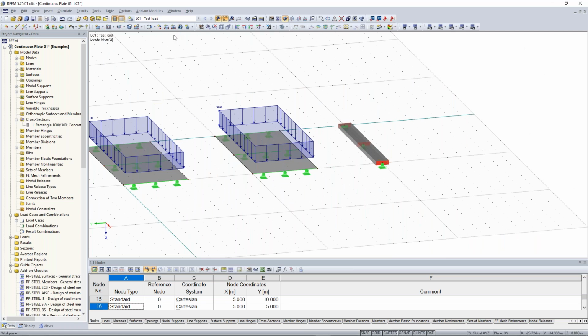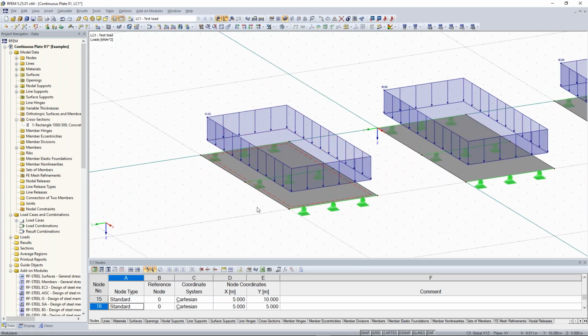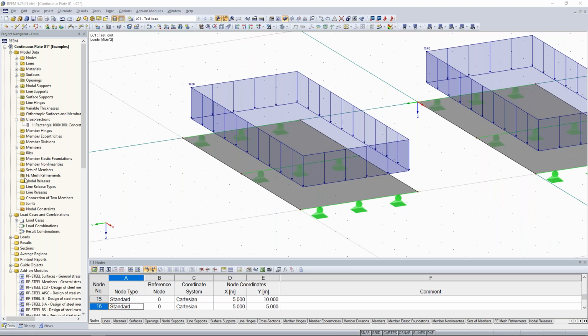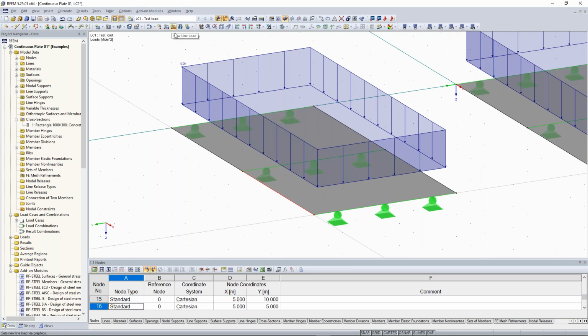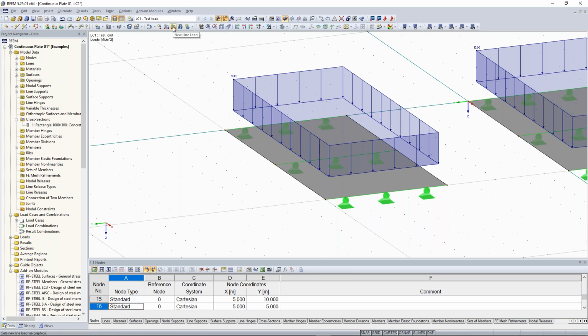One big mistake, especially for RFEM beginners, is to also use line loads for members. But we have to use member loads for members. Line loads are used for additional loads on lines. So when I have here, now I have to look it up, the word, a railing or a handrail on this line, and I want to add some loads, then I can use the line load. Or when I want to consider wind loads at lines, then I can use line loads.